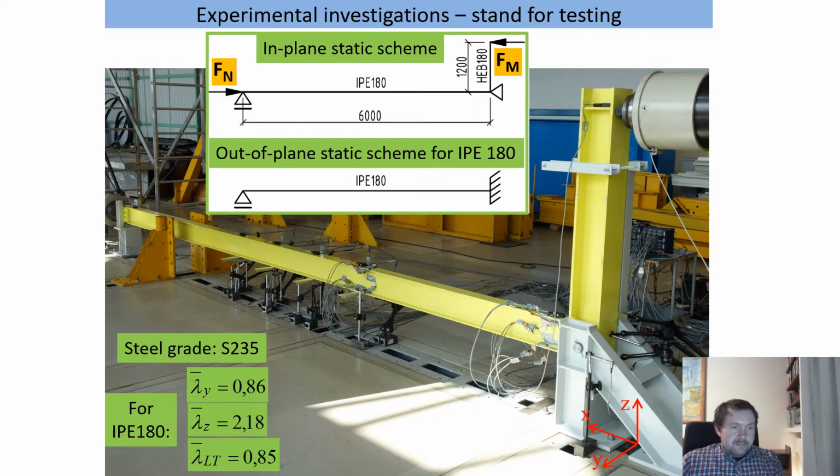flexural minor axis buckling of columns under uniform compression, lateral torsional buckling under triangular first-order major axis bending, and flexural-torsional buckling under interaction of bending moment and uniform compressive force. All specimens were constructed as an angle subframe of the same geometry.